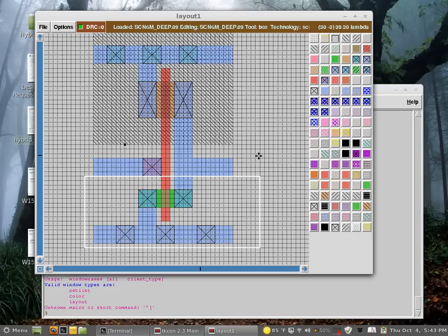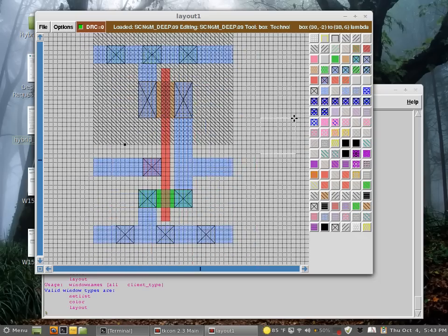all the gates should have the same height, and my XOR gate will be much bigger than this and will have a higher height. So in the end, I have to change the height of my inverter to extend it so that it will be equal to the other gates. But just to prove a point, I just did that. So you have to make it at the end, and do it at the end of our design, then compact everything. Yeah, you can do that too. It's probably better to start with the XOR gate and then do the other gates.